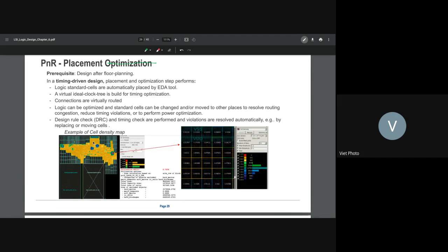It will have to spread all over here because the signal, the data part, the timing part will go from this macro to this macro, from the memory here to memory here. So the cells will be spread all over the place. You see this? This is the space that the tool is allowed to place the center cell. How do they place that?